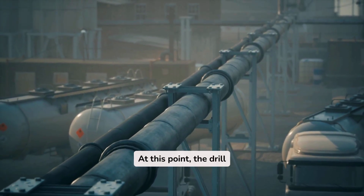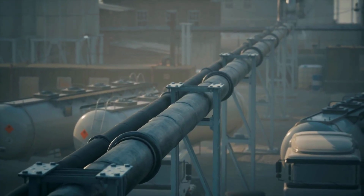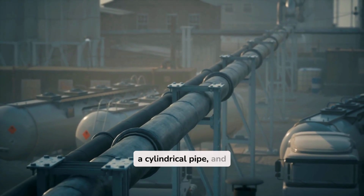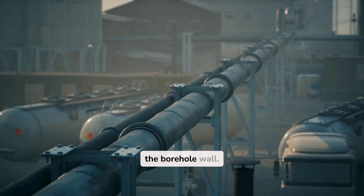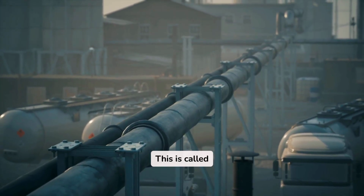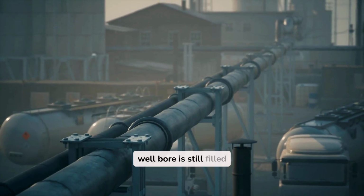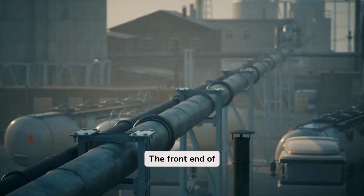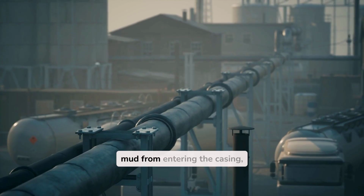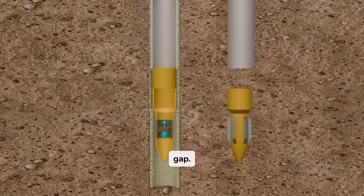At this point, the drill bit is withdrawn and a steel casing is inserted. This casing is a cylindrical pipe, and a small gap is intentionally left between the casing and the borehole wall. This is called the annulus. It's important to note that the entire wellbore is still filled with drilling mud, which also needs to be managed properly. The front end of the casing has a float shoe that prevents mud from entering the casing and helps direct cement into the annulus gap.